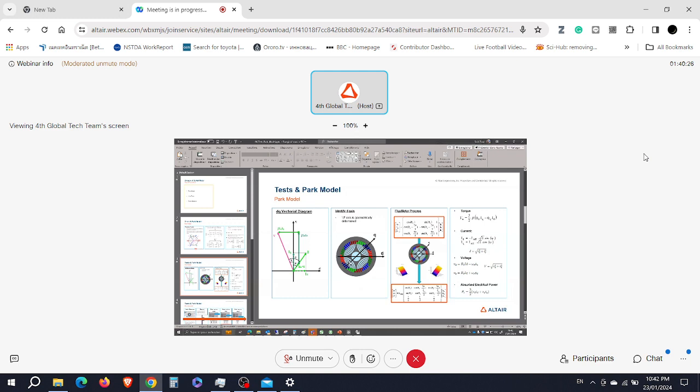It's where we have this pole, if I may say so, and the quadrature axis is here. Since we have a 4-pole machine, it's not 90 degrees but 45 degrees mechanical. But electrically, it's always 90 degrees electrical.